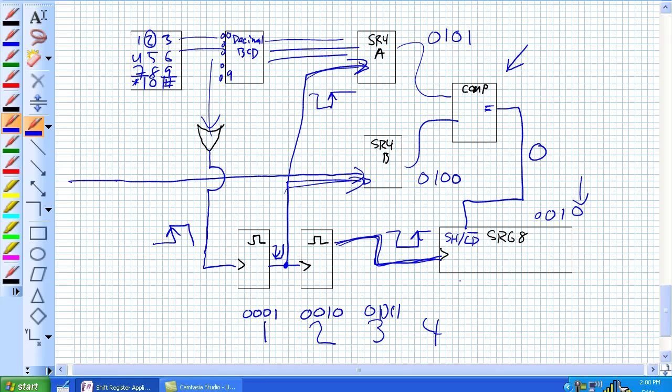And we've generated that clock pulse there. What's going to happen is load. It reloads 4 zeros with a 1 in this position. So you have to start back over at the beginning and do that over again. Whereas had you pressed a 4, that would have been a 1. And finally, that output position would have shifted over to 1, and it would enable some door lock or something like that.